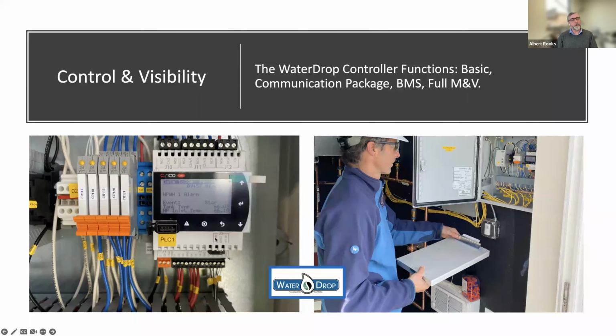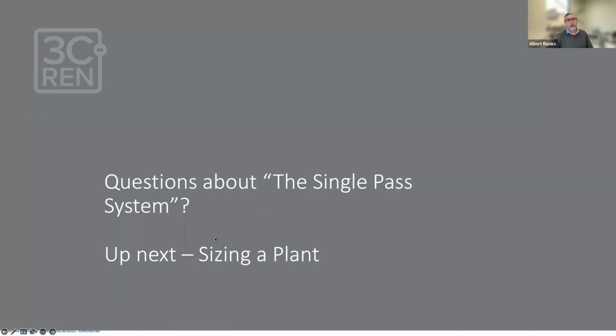It's going to look at tank conditions. And as tank conditions change, it's going to start up the heat pumps. And then it's also going to watch tank conditions at the cold water port going off to the heat pumps. And as it sees the tank condition change and we see hot water showing up at the bottom and starting to head out, that's when it's going to turn off the heat pumps. It has a whole bunch of other capacities and freeze protections and some logics and alarms and things like that. But at the high end, that's kind of the relationship of what the controllers are going to do.